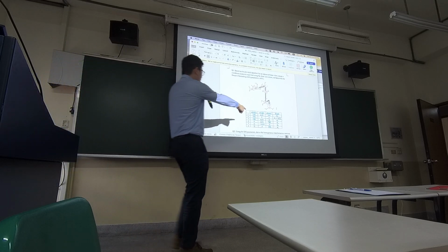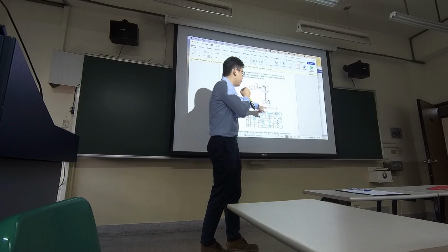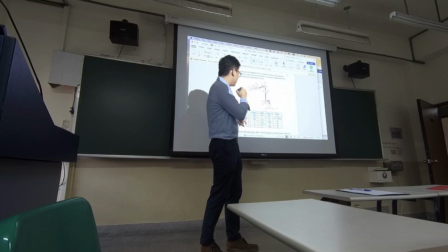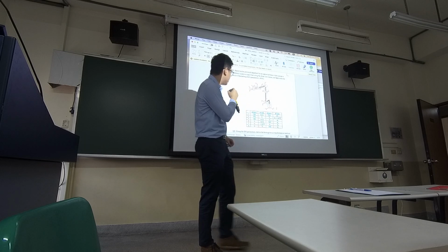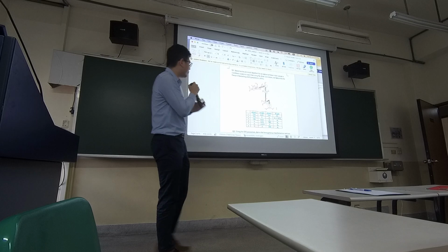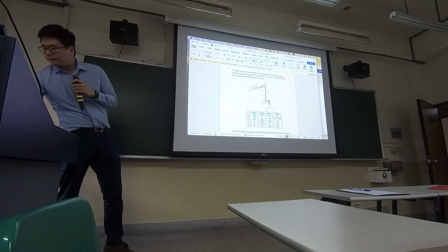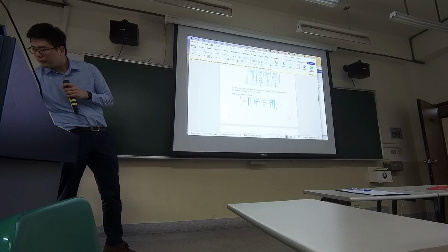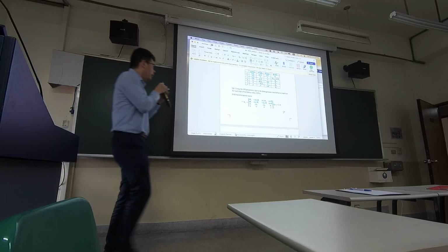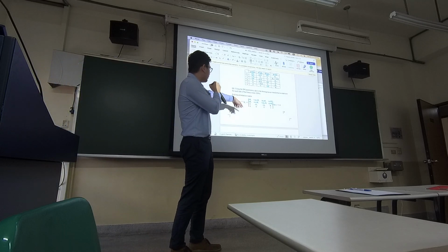And to the definition, this is the DH parameters, and you can generate the parameters. And this is the general matrix function for the DH transformation matrix.